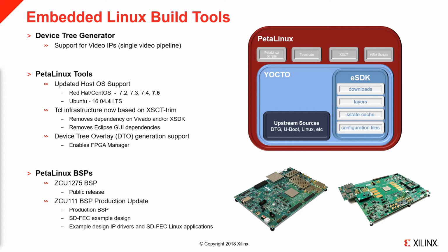In addition, PetaLinux now has support for device tree overlay generation and FPGA manager. This support is useful for designs that need to either load PL logic bit streams after the main system is started or swap PL bit streams out at runtime.